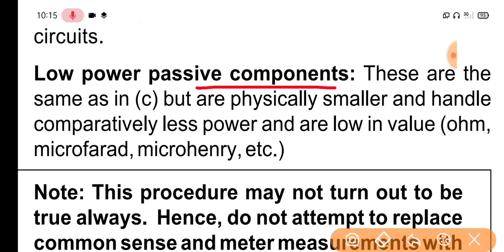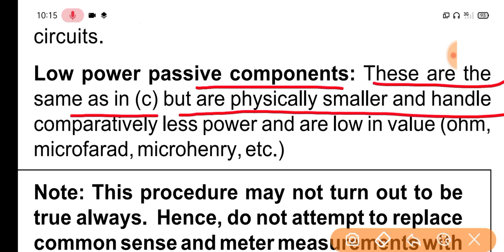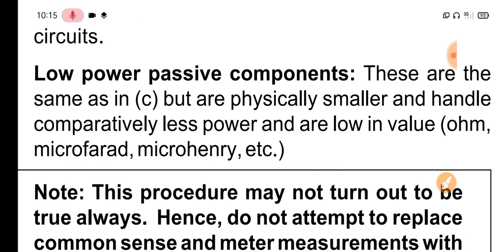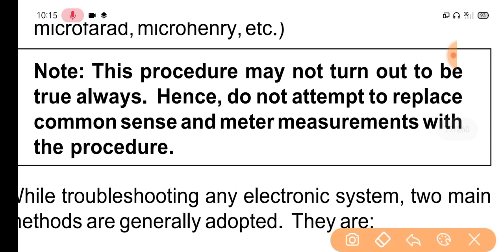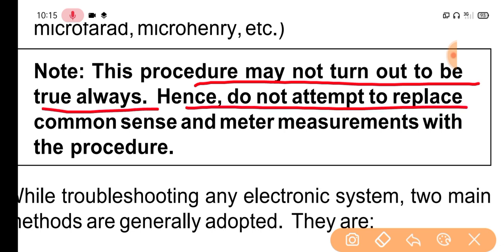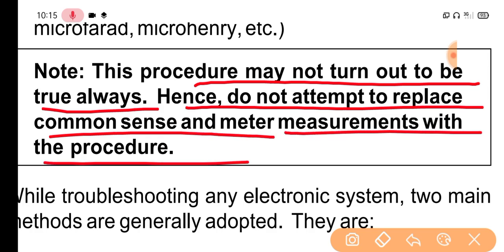Low power passive components are the same but are physically smaller and handle comparatively less power, and are low in value: ohms, microfarads and microhenrys. Note, this procedure may not turn out to be true always, hence do not attempt to replace common sense and meter measurements with the procedure.